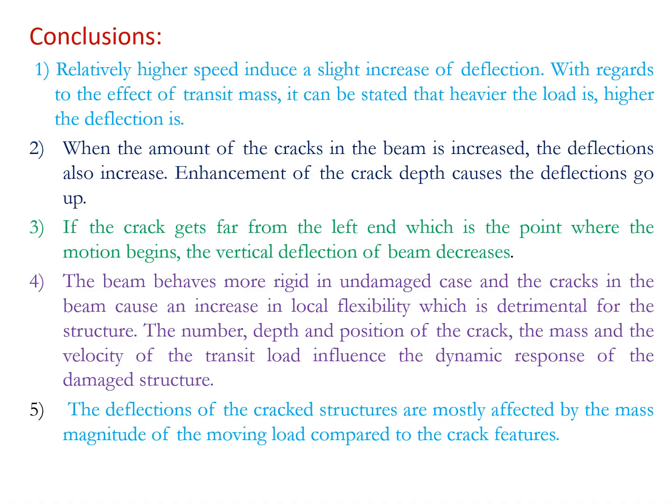So coming to the conclusion, whatever we have discussed here: the beam deflection will increase if we increase the moving mass and the crack depth. Again, if the crack location gets farther from the left end, which is the point where the motion begins, the vertical deflection of the beam starts decreasing.